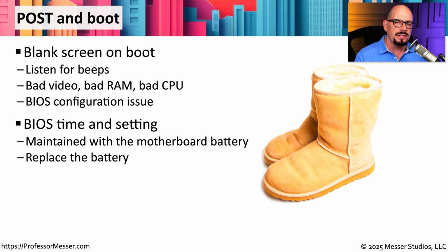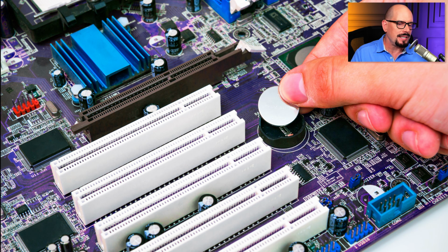This means we could move the computer, plug it back into a power source, and the computer already knows the date and time based on that clock that's keeping that updated when you're not connected to power. If your battery has failed, you'll be prompted to input the date and the time each time you plug in that computer and start it back up again. Simply replacing the battery on the motherboard will resolve this problem.